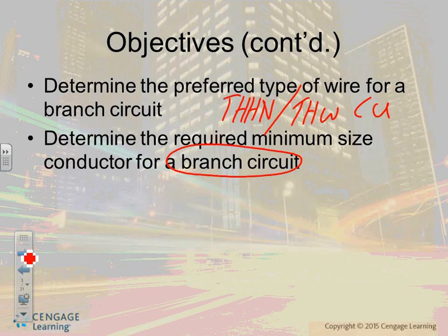You always size the branch circuit, guys, and the conductor and overcurrent protection device based on what? The load. Always the load. Give me the load, I get your branch circuit. Let me go over that one. Residential 15 amp circuit. What do you use 15 amp circuits for in dwellings? General receptacles and lights. 20 amp circuits: bathrooms, kitchens, laundry. These are dedicated circuits.